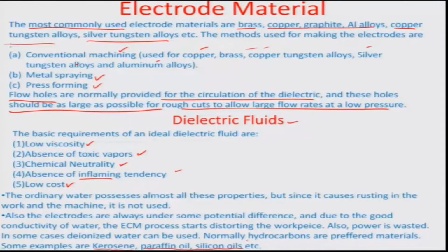These are all hydrocarbon based materials which are preferable for this purpose, and the basic dielectric can also start from ordinary water which possesses almost all these properties. Only thing is that in case of water, particularly when we are machining steel, there is an additional problem of rusting which may come out, and it may not be a very good choice. So, that is why one shifts to hydrocarbon oils rather than water.